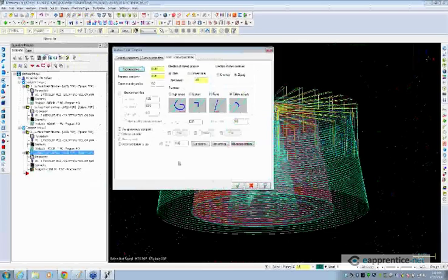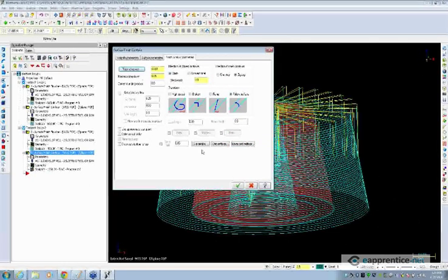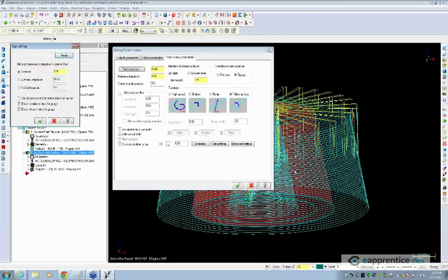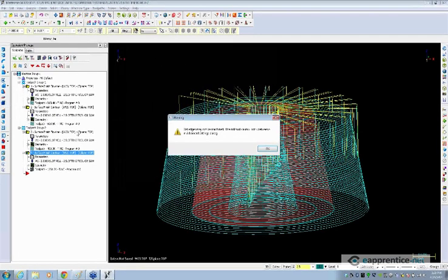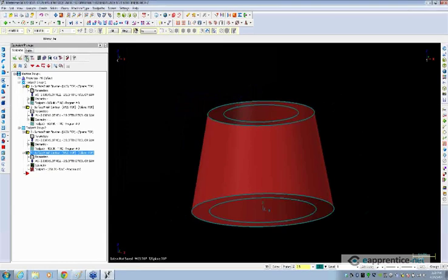Now, in order for us to do motion on the undercut, we have to turn off these gouge checks right here. So this is gap settings. We can define our gap distance, and we need to go ahead and disable check transition motion for gouge and check retract motion for gouge. So we have to disable those in order to allow it to do undercutting. So we'll just make one change at a time here.